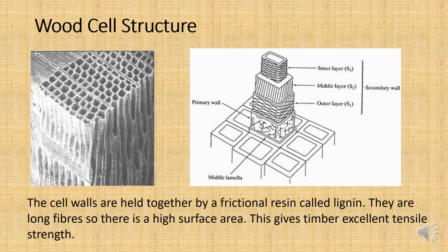If I had a piece of wood and I was pulling it apart, one end I'm pulling and the other end I'm pulling, and I'm pulling parallel with how these cells are aligned, it's going to take a lot of load before the wood will break. Timber has really good tensile strength, so long as the tensile loading is parallel with how these cells are arranged. That's a very important thing.